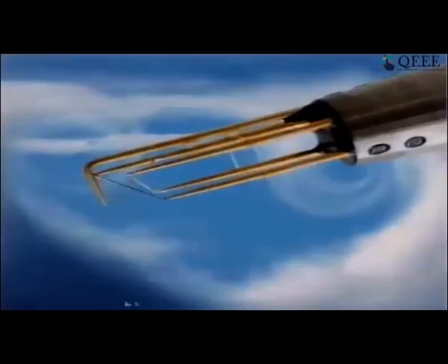let's come to boiling. Oh, sorry, before I come to boiling, let me just give you a few ideas of a probe that is used to make velocity measurements in an air flow or a gas flow. This is called a hot wire probe, and what you are seeing here is a base whose size would be of the order of about 5 to 8 millimeters. On top of that are these prongs. They are coming out, they are coated with gold, and between a pair of these, you can see there is a wire connected.